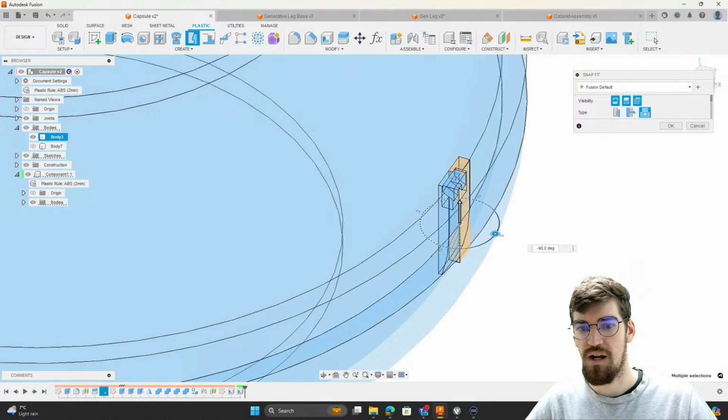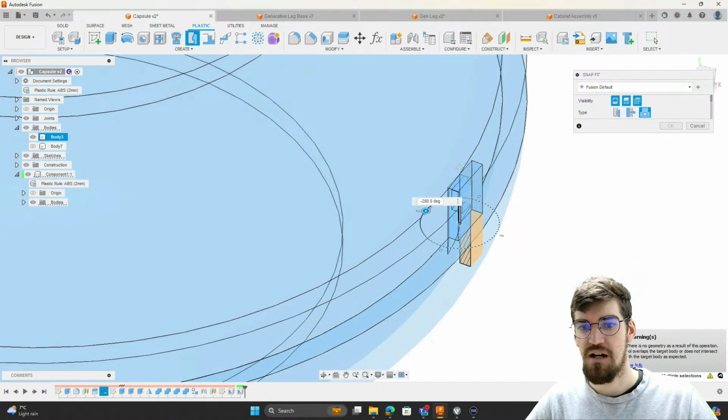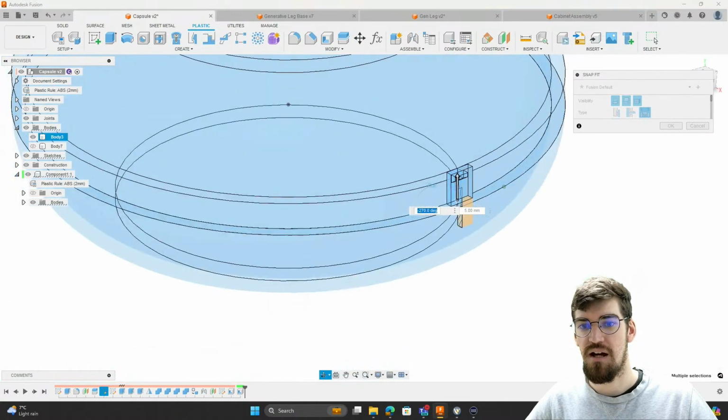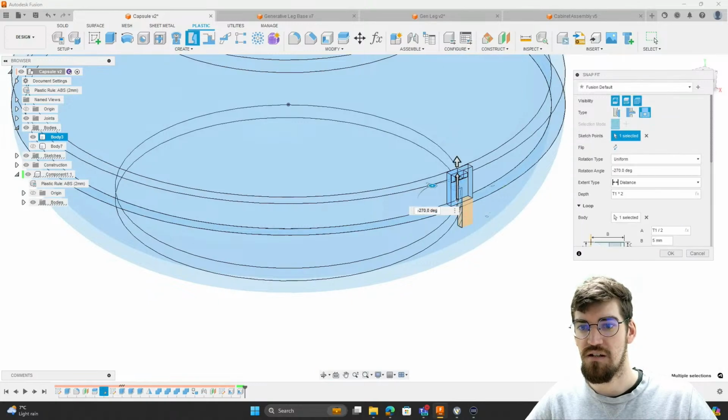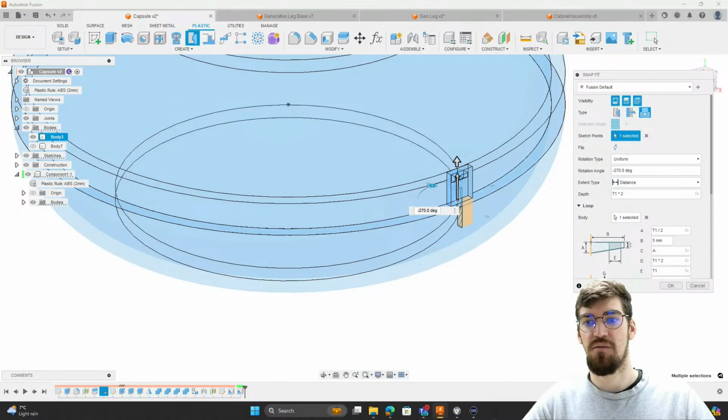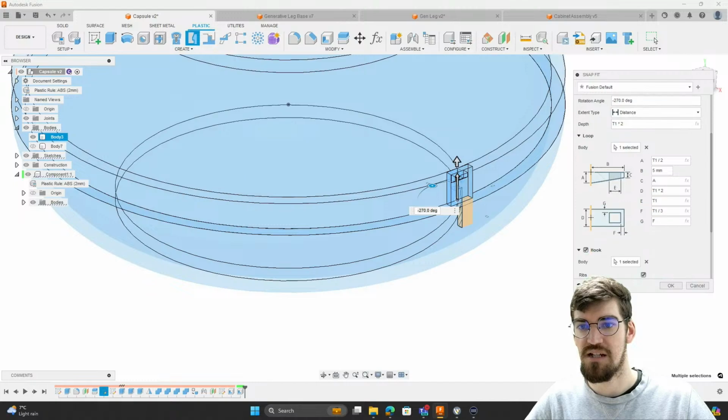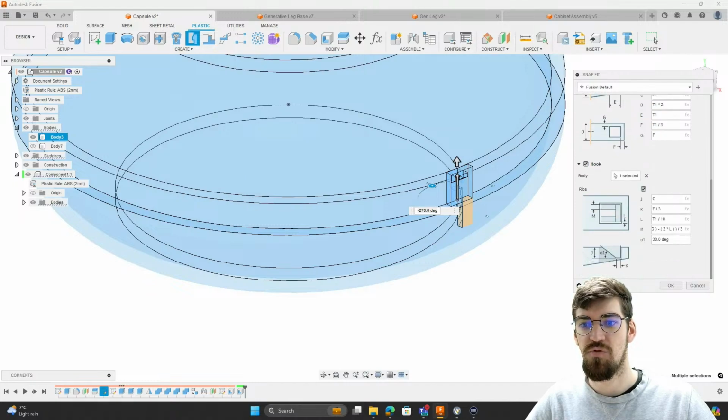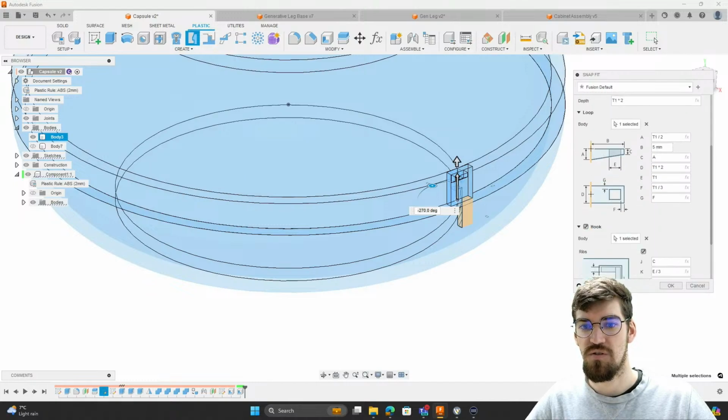Again, depending on where I want this located, that's all driven by the sketch itself, and at this point in time it's cutting through the top component whilst adding geometry to the bottom component, so we can simultaneously add and remove geometry from the two.